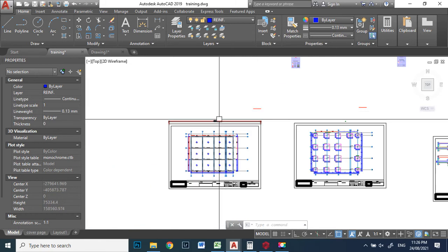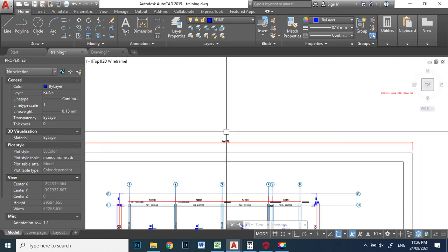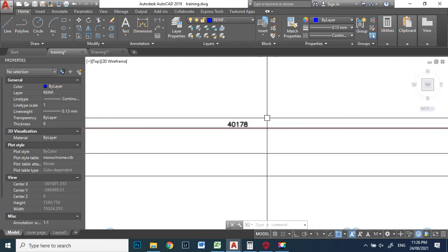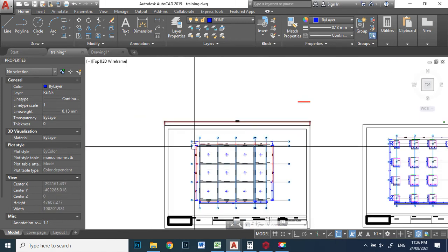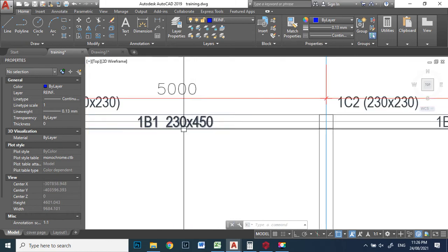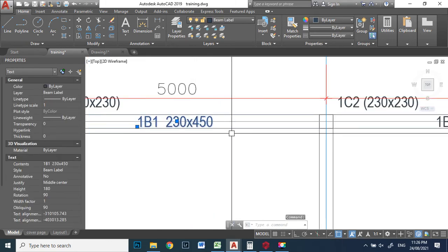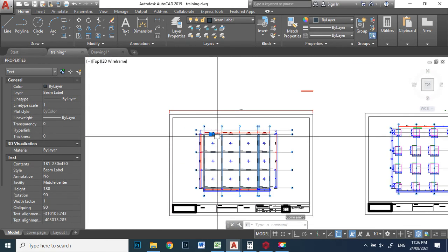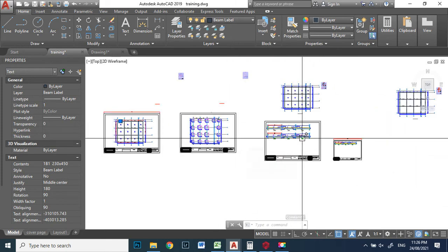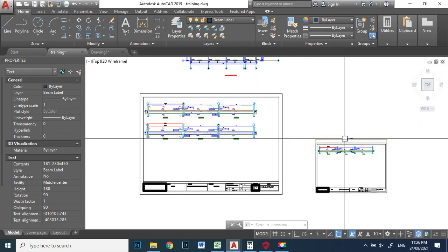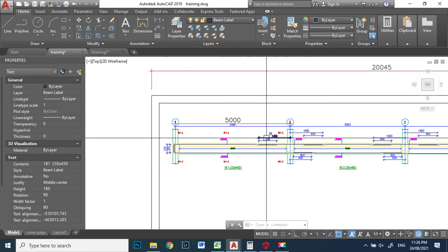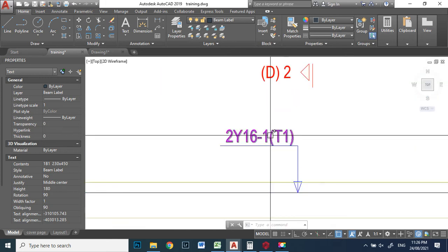We print with A3, so that will be the standard, which is now 42,000 by 29,700, where the height of your text is 180. Same principle, anyhow you do it, you scale it. If you're increasing it, you scale it like that to get your height.